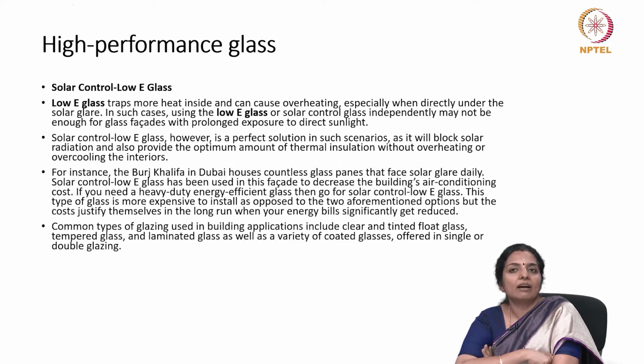If you need to have heavy duty, energy efficient glass, then we must go for solar control low E glass. This type of glass is highly expensive to install as compared to the two options we've discussed before. But the cost justifies itself in the long run when the energy bills significantly get reduced.